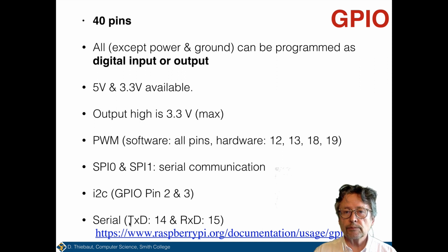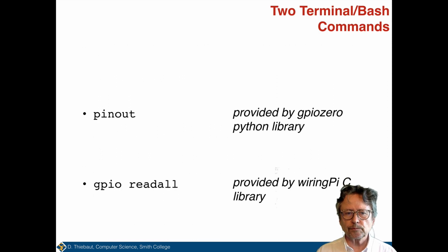And then serial, we can do serial as well. Pin 14 and 15 correspond to transmit data and receive data. But again, it's 3.3 volts, so we have to be careful with that. Good link here to all this.